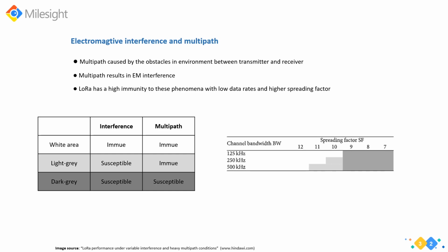So that's why LoRa is so suitable, so perfect for long distance data transmission, to resist this kind of interference. And if you always enable the adaptive data rate mechanism, or if you deploy the gateway close to the sensors, that would be helpful as well. That would help the devices to resist this kind of interference caused by the multi-paths.